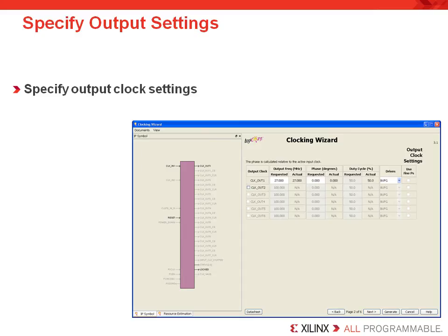While most designs will benefit most from being routed globally, routing local control or low fan-out control signals on regional buffers will maximize the use of the global routing resources and save power consumption in your application. The benefit of the global buffer is that it will help compensate for your skew. It is effectively a big fat wire. The buffer will also reduce your clock skew, but is designed for local clocks and less skew.